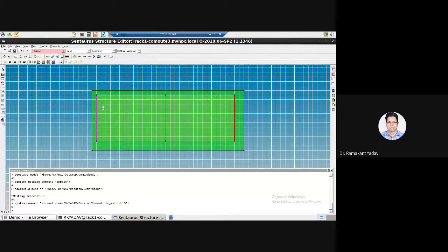Now, to apply the different voltages, this is N region, this is P region. If I want to see the current voltage characteristics, what I have to do? I have to apply the positive voltage here and zero voltage here and change the voltage, because the current of the diode will be changing with the voltage. So I have to sweep the voltage from 0 to 1. Let us apply 1 volt. So 0 to 1 and calculate the value of I for different values of this. So that is the second part of this.